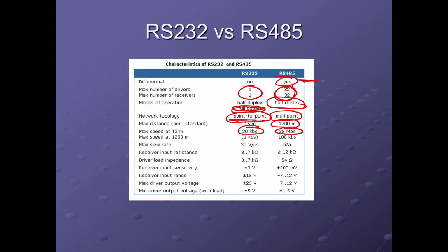So even though we don't do any labs involving RS-485, you can understand it's the same type of asynchronous serial connection, but whenever you're looking to multi-drop, you would want to go with RS-485, or if you wanted to even extend your distance officially, look at that distance for 485. 1.2 kilometers is the maximum cabling distance. Okay, so where does that really put us? Well, in terms of this course, what we want to do is understand that 485 has a number of advantages, and you could use this table or anything else to list the advantages, but we're very specific in terms of our curriculum and our quiz question.